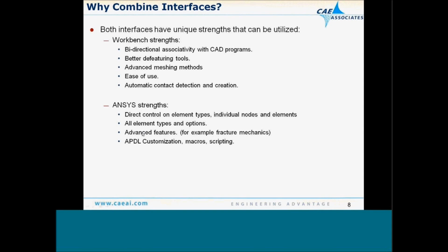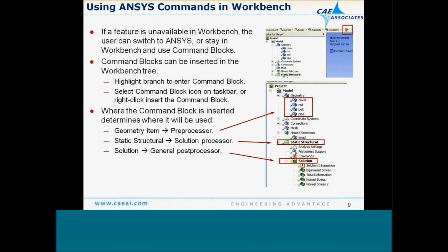So that would be the reason to use Workbench, but there might be just something specific that you want to tweak with a command block, like maybe different element types, put in some material properties, or change some settings here and there in the analysis that might not be available in the Workbench GUI. So that's where command blocks come in. You just make those changes that you would like. And you might also have some scripts that you're used to using all the time, doing some post-processing, setting up different things. You can still use those scripts. You just need to stuff them into a command block. So that's kind of high level what we're talking about here.